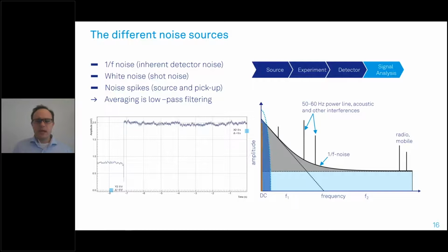Now let me quickly also combine this with the signal input noise, because often we are asked, I want to buy a lock-in, maybe I should really go only for the very best in signal input noise. In general, this is always a good idea because noise adds up in quadrature. So noise always piles up, and the less noise you start with, the better.